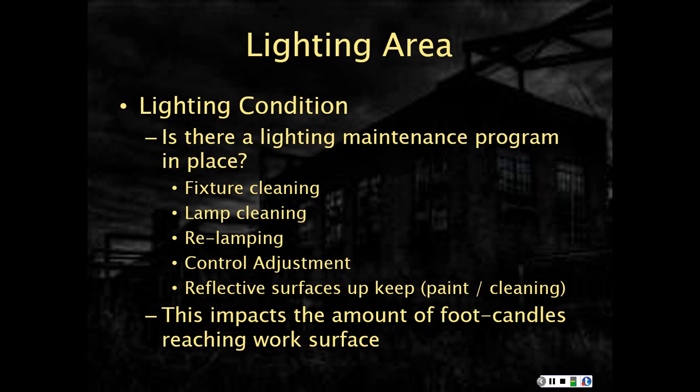Is there a need for a control adjustment? So are timings on lights appropriate? If we're using an occupancy sensor, are those adjusted right? If it's a more elaborate lighting schedule, do the schedules make sense? Have they been updated to match what the current building usage is?